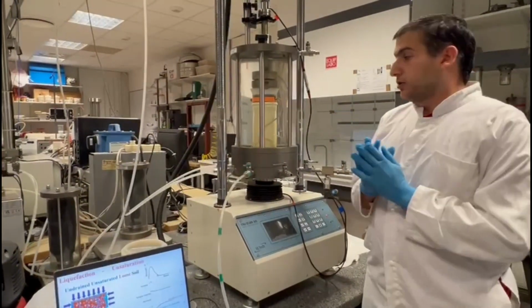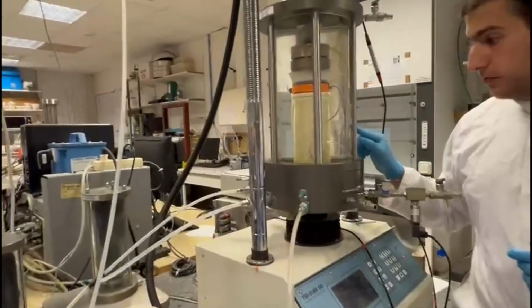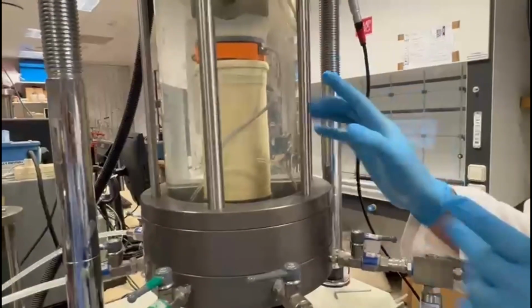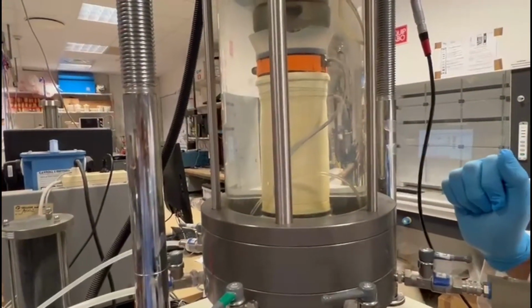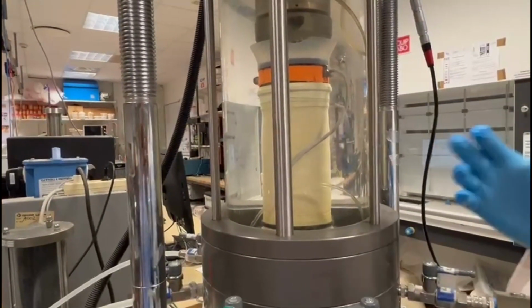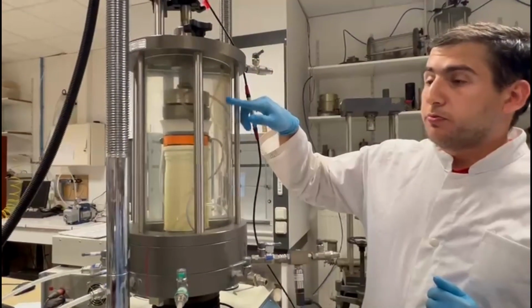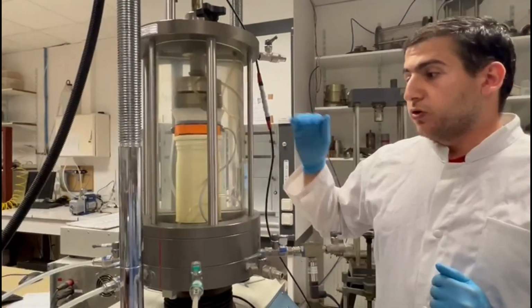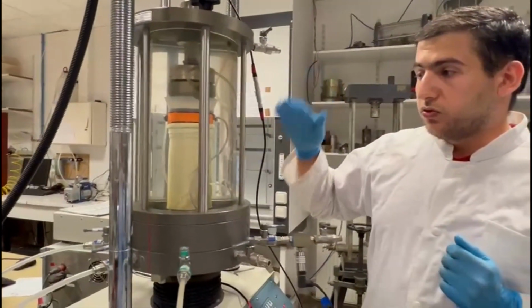To apply a confining pressure, we have our soil, which is in the yellow membrane that is found here inside the cell. And around this yellow membrane, we have the water that we will use to apply the confining pressure on the soil. And inside the membrane, there is the soil that we will saturate or desaturate depending on our need to duplicate the phenomena. And we will apply, using a piston, the dynamic load on the sample, positive and negative, to liquefy our sample.